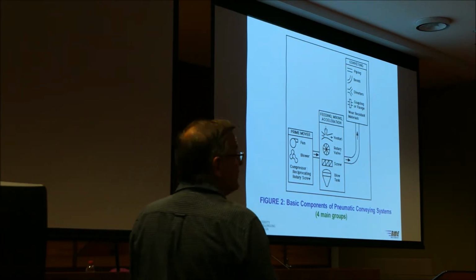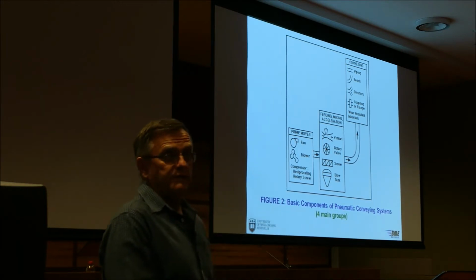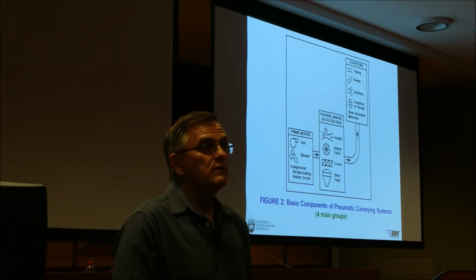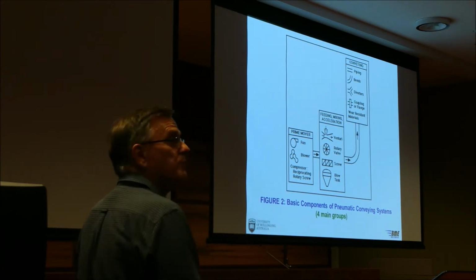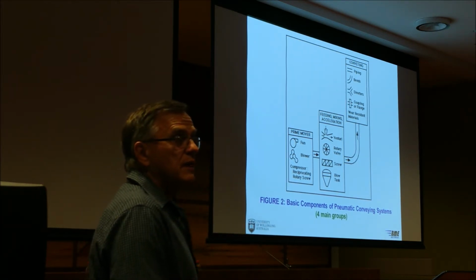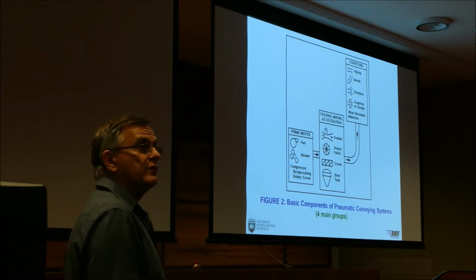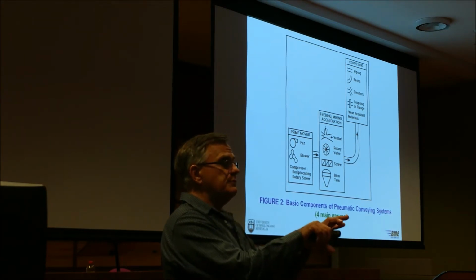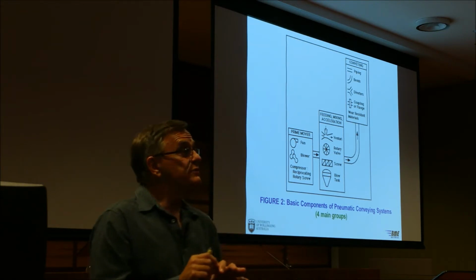And also diverters. You may need to go to silo A, B or C. You need a diverter valve. And that's not a trivial task. You just don't pick any valve off the shelf. You've got to make sure it's suitable for the product and the application. How you connect your pipes or tubes can be important. Particularly if you've got food product going through there, you don't want simple flange connections, because flanges will be misaligned and you can get a dead spot, which attracts bacteria.